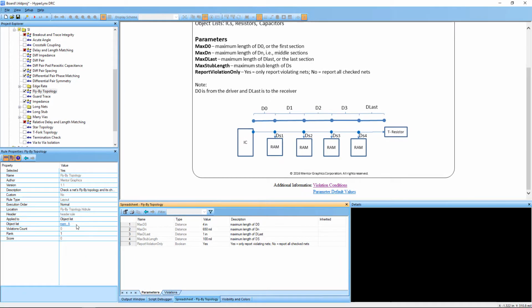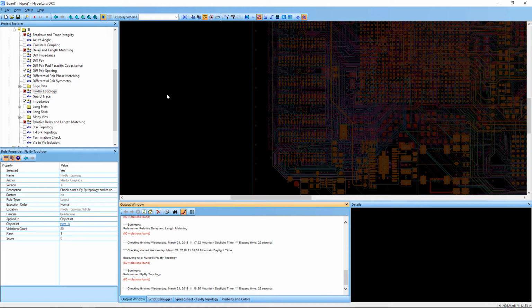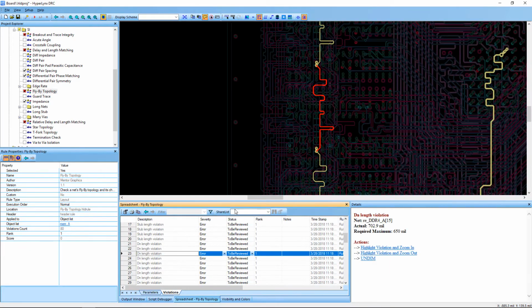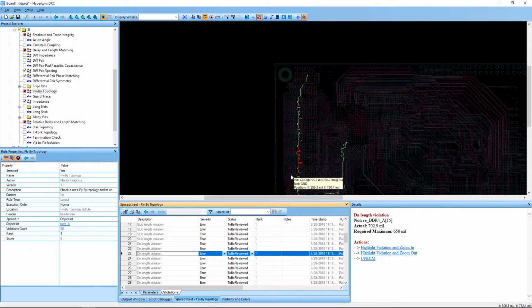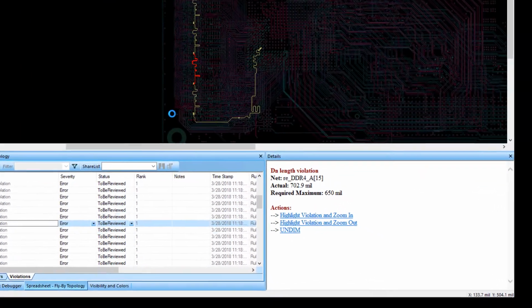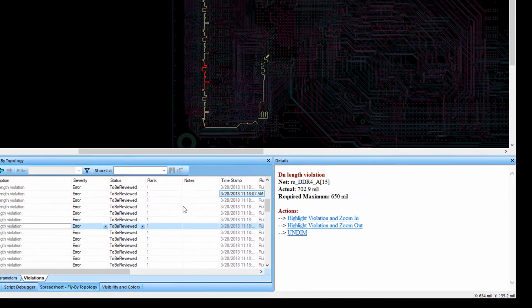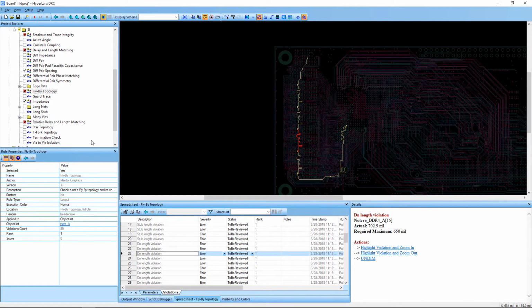In your design datasheet or your specs for your PCB routing guidelines, they will tell you the typical delays to expect between each. HyperLynx DRC makes it very easy to identify automatically where we exceed our route lengths in this topology for the memory routing. Now let's switch gears a little bit and use the signal integrity category rules to focus on some SerDes nets.